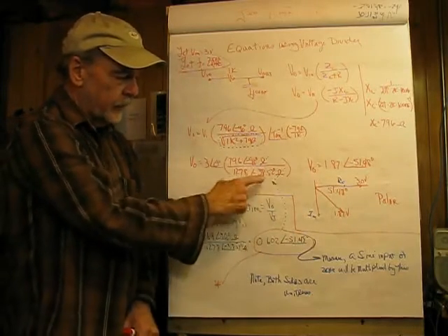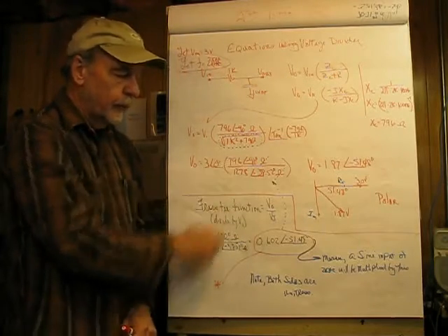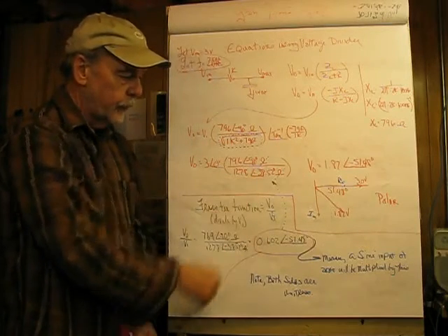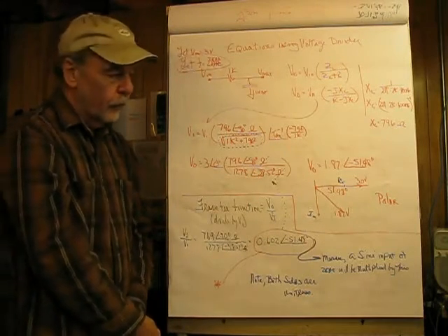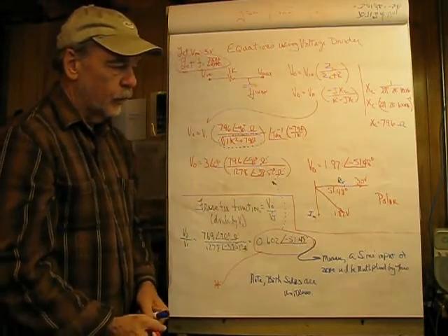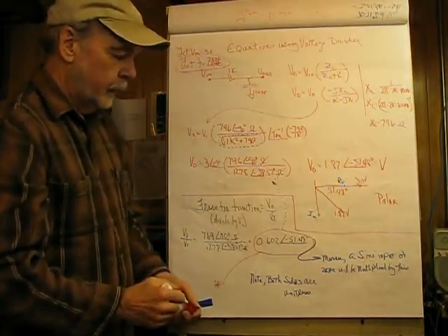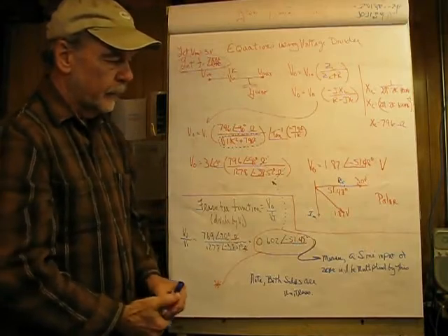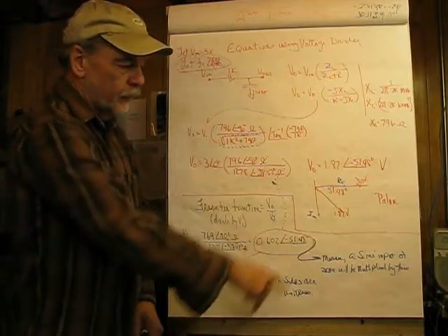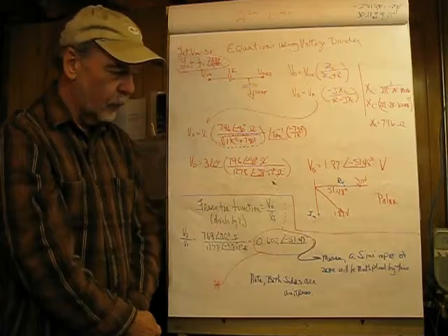And we subtract the angle in the denominator from the angle in the numerator, so this is going to be negative 90 degrees minus a negative 38.52. So that'll give us 1.87 at negative 51.48 degrees volts. And once again, if we were to plot that, in here we would have the 51.48. And since I don't have a negative here because I'm showing this in a graph as extending into quad 4,